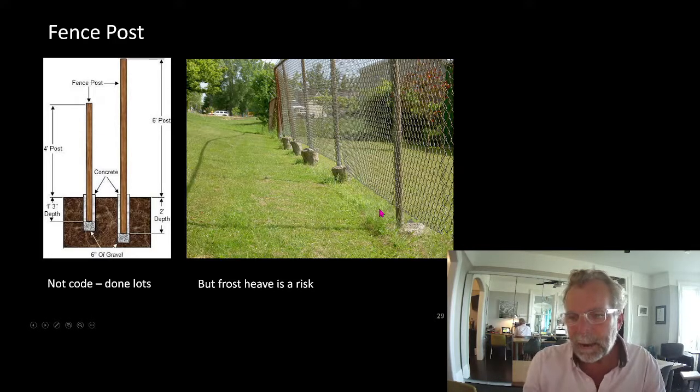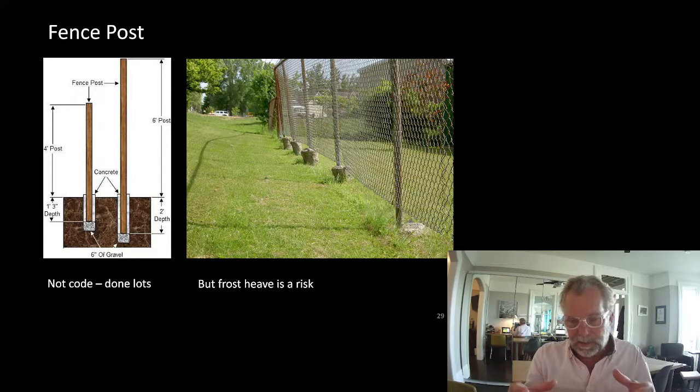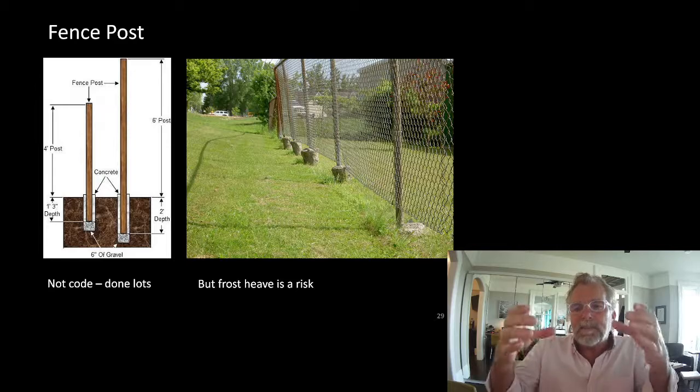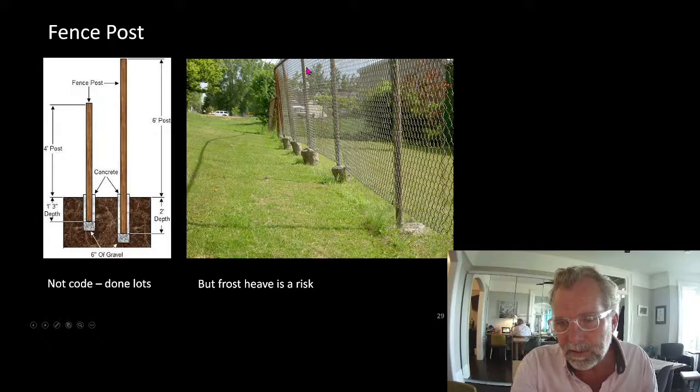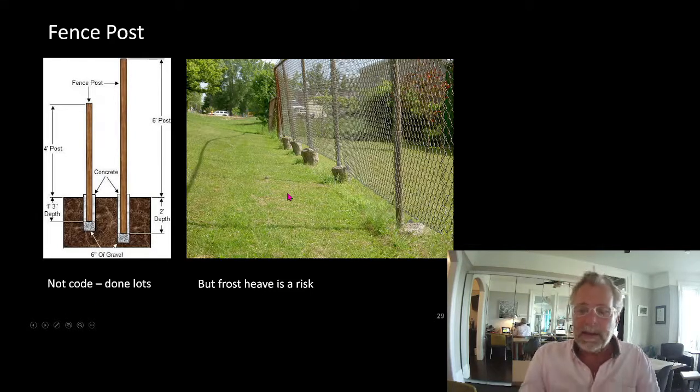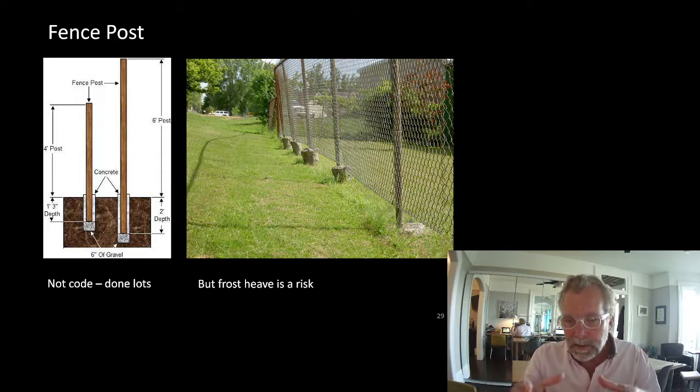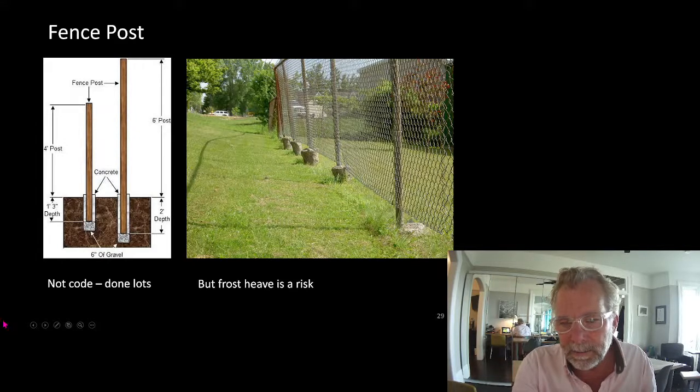Frost jacking happens because of adhesion heaving. So we can have heaving from the bottom. That's the regular heaving. Heaving from the sides is called adhesion heaving. So adhesion heaving results in frost jacking. So we put a sonotube around that. Now the sides of the concrete are smooth. The sonotube is cardboard, which eventually just rots away, but we wind up with a smooth side on our drilled pier, and we don't get adhesion heaving.